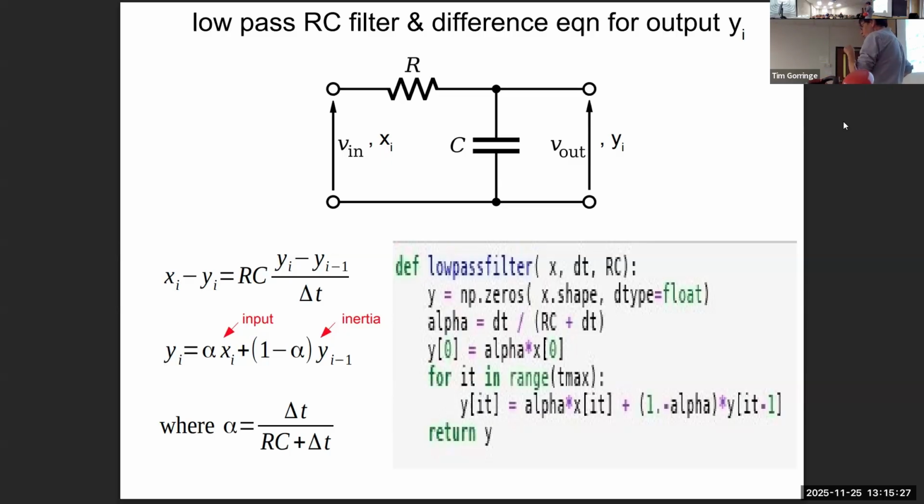So here what has a characteristic time constant is the combination of the resistor and the capacitor. I'll call it a time constant. It sets the scale of charging up or discharging the capacitor, and that is the product of R and C. So it's like the characteristic time for moving charge from one plate to the other through that resistor.